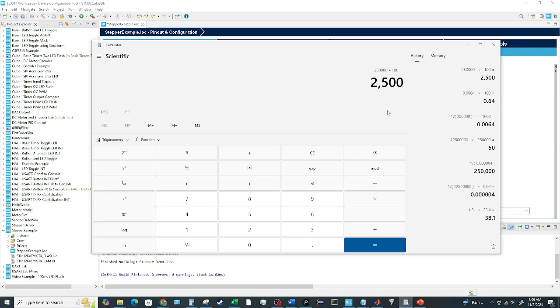You really need to think about what the actual range of speeds is that you want in this thing. For me, this is just an example, so I'm not going to get too exact. But I would think something on the order of maybe 5 revolutions per second is moving pretty fast for a stepper. So maybe that's an upper limit, and the lower limit would be limited by our total period. So that could actually be pretty long. We can have this thing go as slow as we want, and then we're up against the limits of the actual stepper motor itself. So I think this will work.